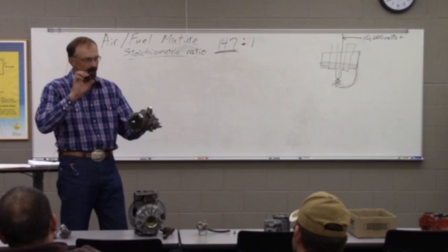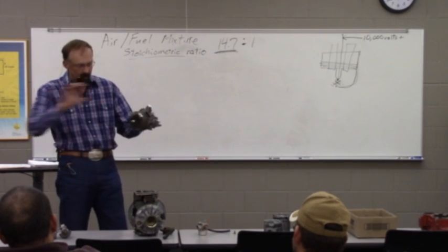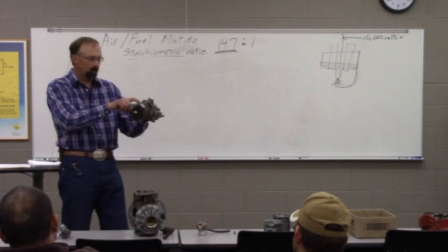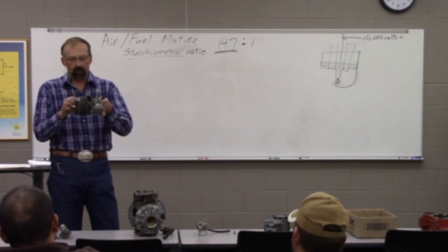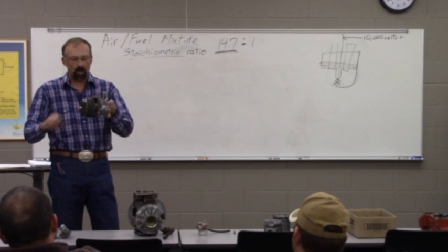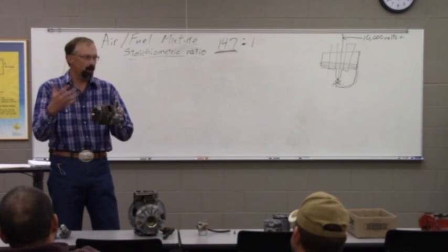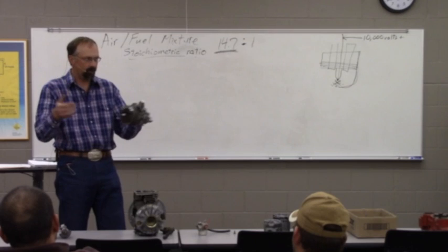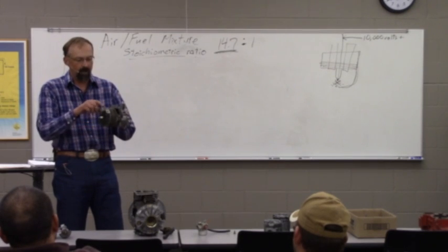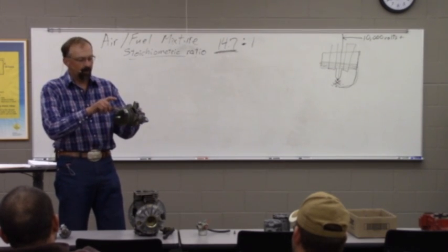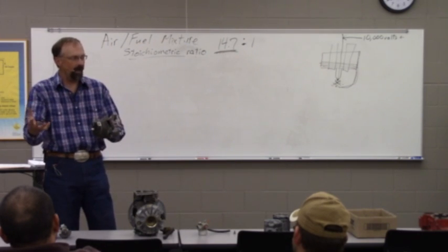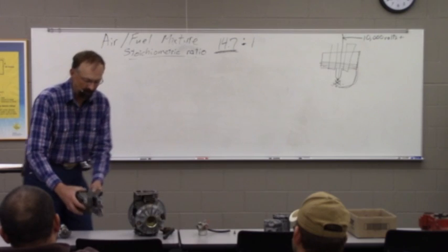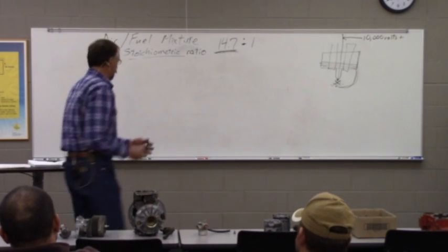The heat will transfer out of the water into those metal tubes. Those metal tubes all have a whole bunch of little fins like this, and the heat transfers from the water, we're going to call it water, it's a liquid glycol-based mixture, into the metal. Then from all those little fins, it's going to transfer from the metal into the air. Because we have way more heat than we can work with, we need to get rid of it.